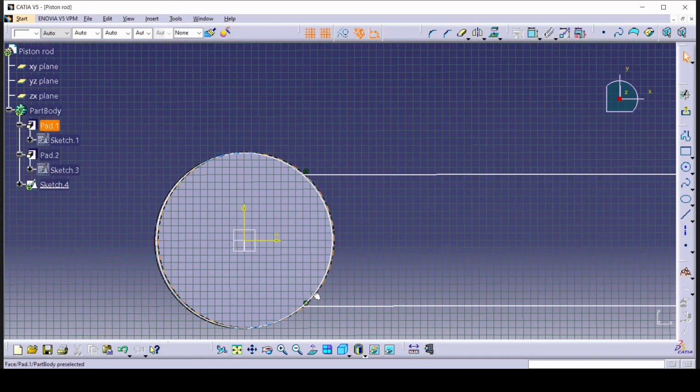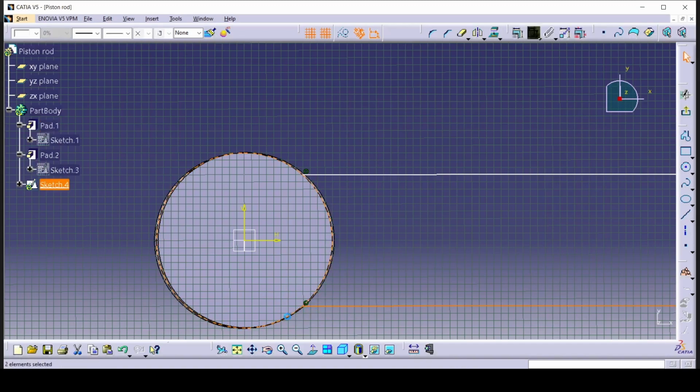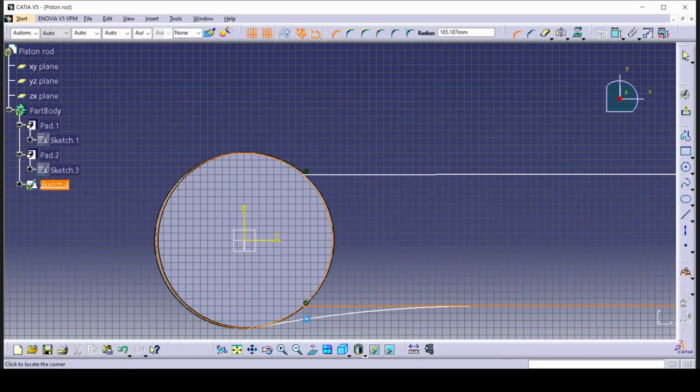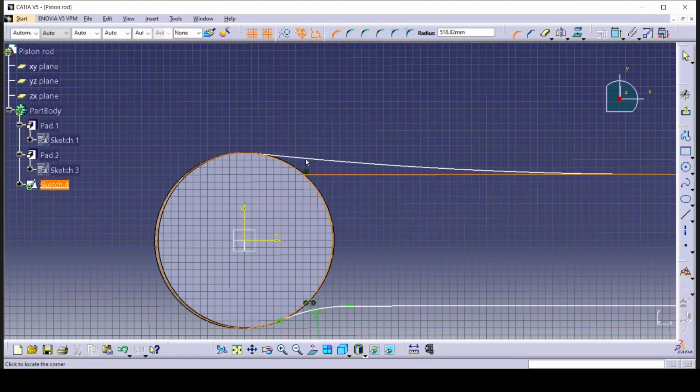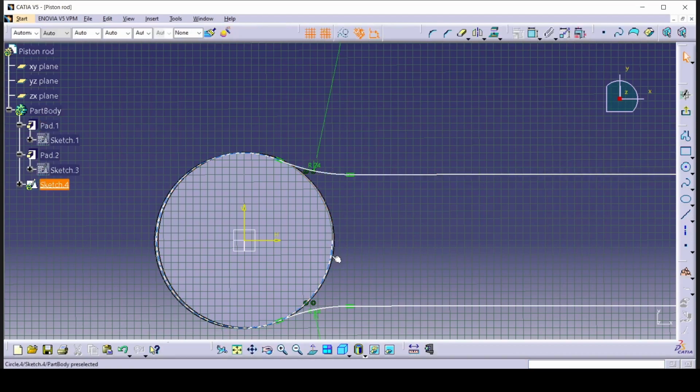But we'll probably have to need the circle again. So we want this 24. We'll need the circle again, which is kind of annoying. So let's select the circle and the radius, make it 24. There you go. Delete this circle. As you can see, it did not delete itself in half completely.